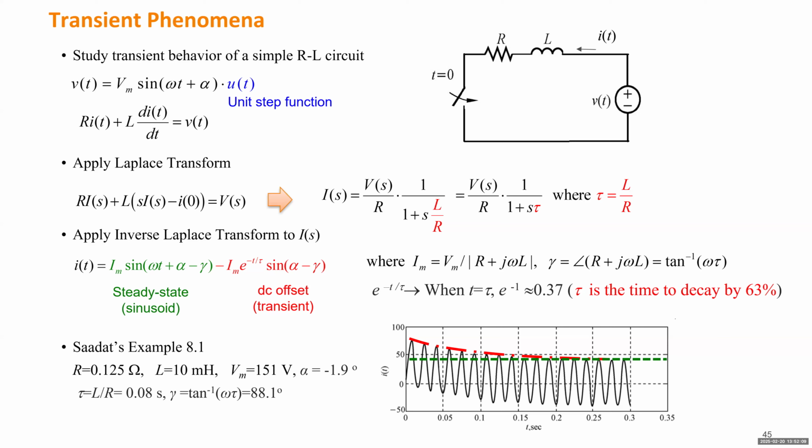Those L's and R's correspond to the branches, or the part of the circuit, that really characterize the dynamic of that time frame. Then you can ignore anything else. That largely simplifies the circuit to only this one. There may be many other L or R, remembering how many branches we have in the equivalent circuit, but maybe only one L and one R are really important for that tau. Eventually we can utilize just a simple circuit to study each type of dynamic. That's what we're doing right now.